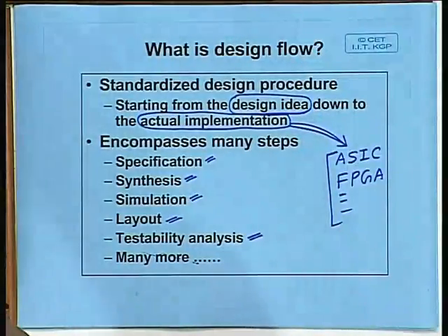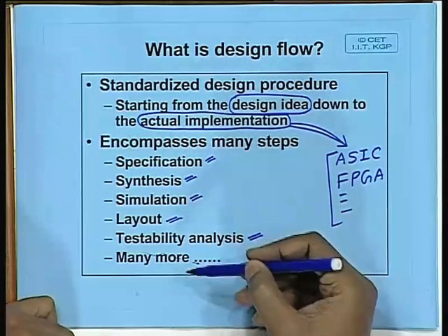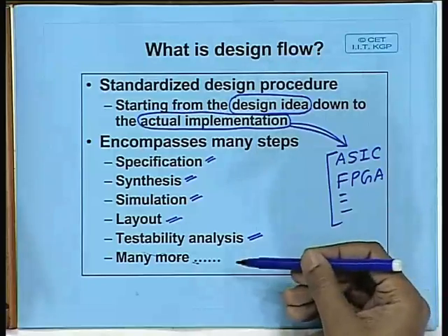Now, here I have just told you that you today have chips which can house millions of transistors, but externally you can have only a few hundred pins available to you. So, just using those few hundred pins, how do you test those million components inside? There has to be some special design effort that has to go in during the synthesis process itself, so that during testing it becomes easier for the test engineer to test the chip. There are a number of techniques called design for testability, built-in self-test. These are the things we will be discussing.